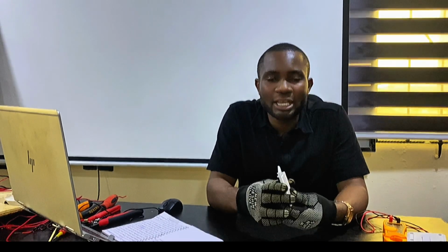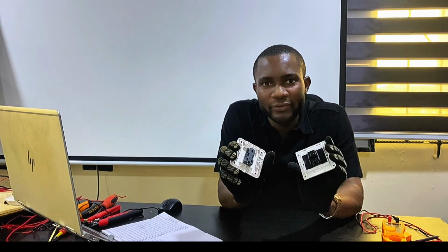This is called an intermediate switch, while this is called a two-way switch. Can you spot the difference here? Now, looking at this carefully, this is your normal switch that you know. It's called a two-way switch. The two-way switch has 3 terminals. You have the common, you have the L1, and you have the L2.